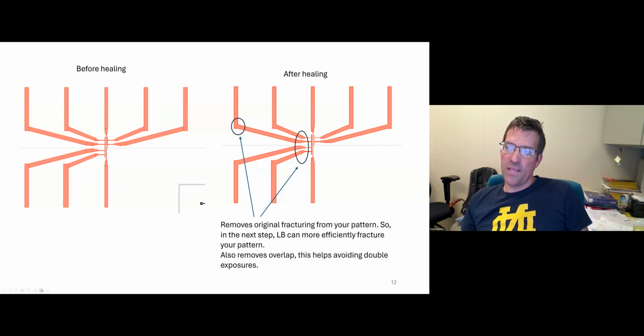So it's not just the proximity effect, as Professor Bernstein discussed previously, you will actually have a double exposure. So you can pretty much guarantee that 2 lines that you position very close to each other in the center will be overexposed and probably touching. You don't want to do that.